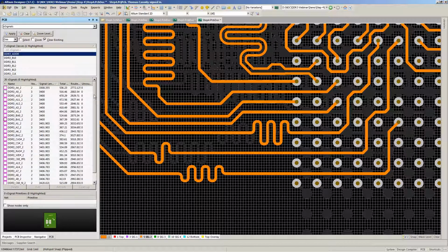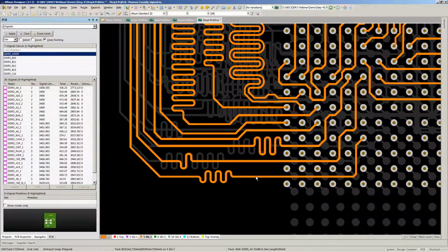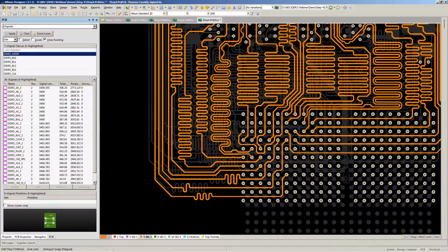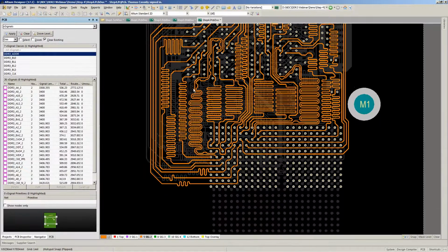And then just as a quick aside, Altium lets you export these values relatively easily to a spreadsheet. So I take advantage of that to create a custom spreadsheet that lets me convert these lengths back into distances. And therefore I can double check that, based on the dielectric constant of the internal versus outer layers and the final lengths, I can just verify in the time domain that things are still pretty close, as opposed to verifying in the length domain.